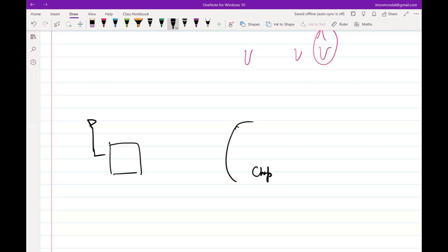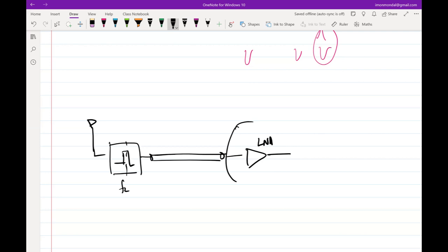You have a SAW filter that we discussed in the last class, centered around FC, and you have a long transmission line, right? And then we would like to have an amplifier, and we call this LNA, right? And we said that in order to minimize reflection at the LNA side, we have to ensure that this impedance is exactly equal to Z0. Otherwise, you are going to have these multiple pulses, multiple echoes at the LNA input, which may or may not be good, right? So it can amplify your signal, or it can destructively reduce some part of your signal, depending upon how many reflections you have.